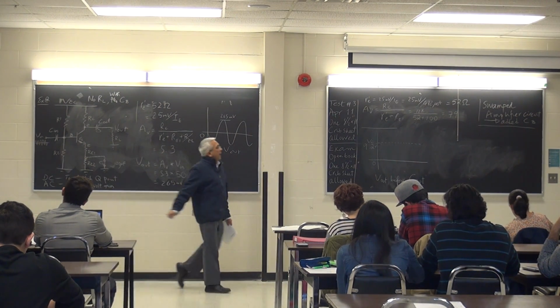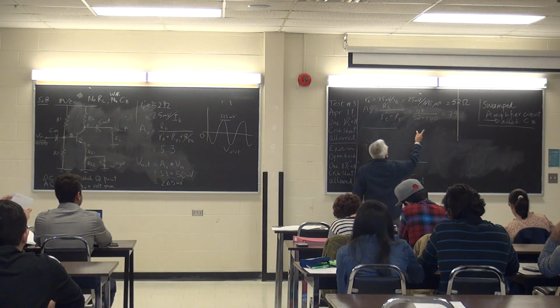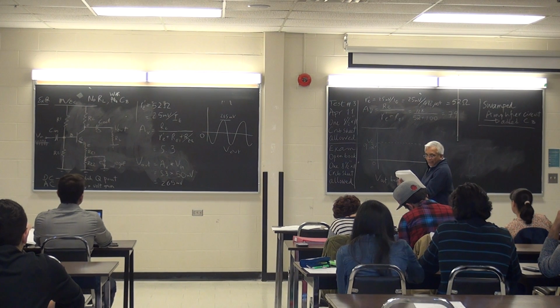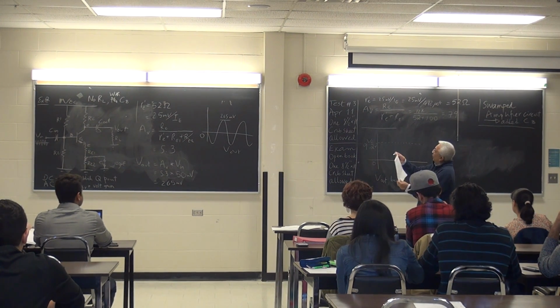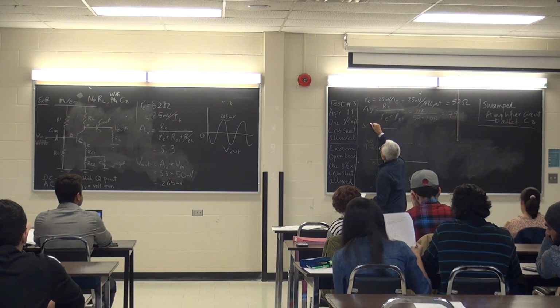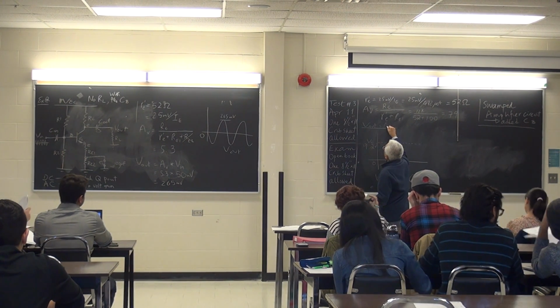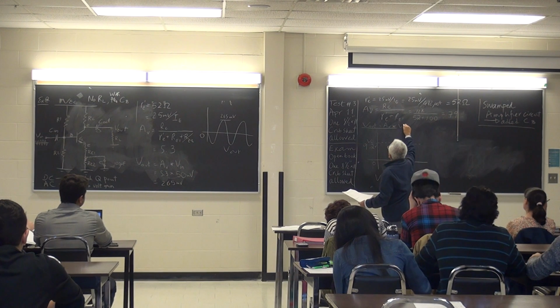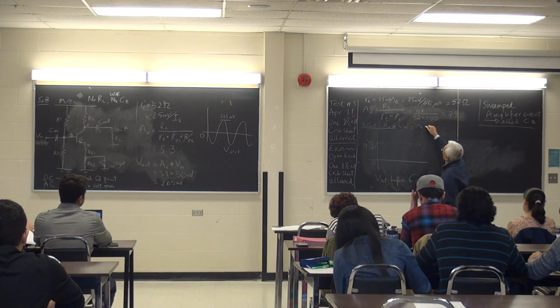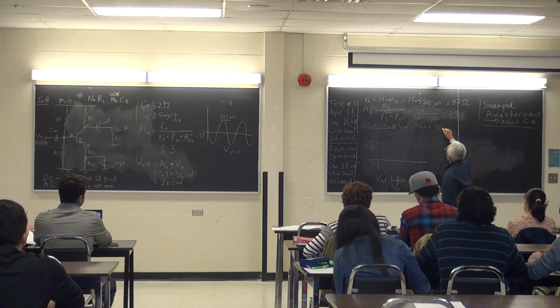So now what happens is my signal, which is 79 times bigger, is going to be riding on top of that. Did I forget to do a calculation at the bottom of page 10? V out. AV times V in. So that's 79 times 50 millivolts.